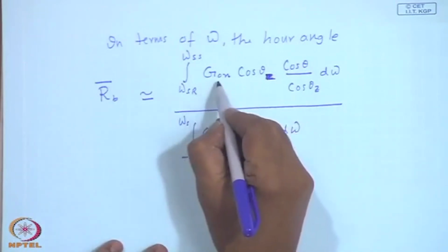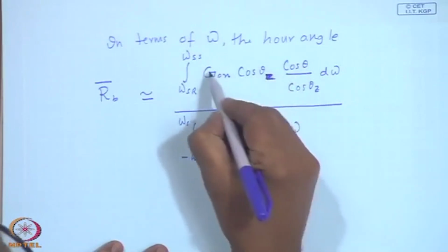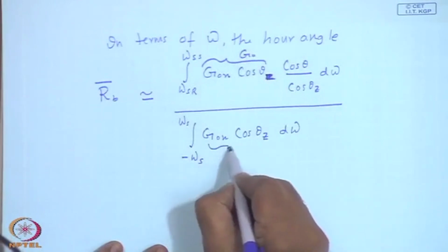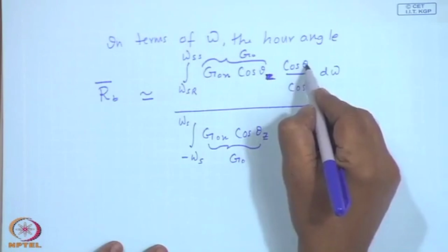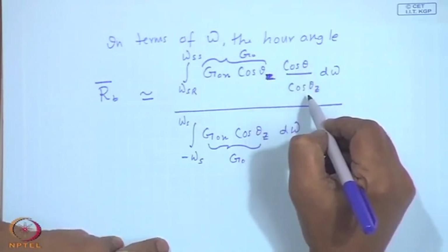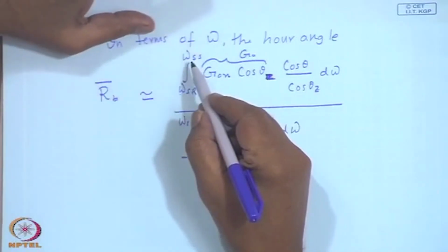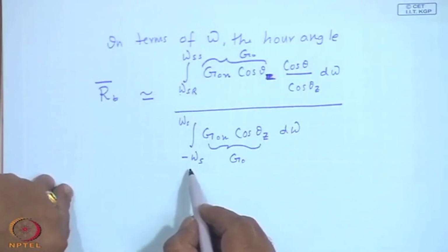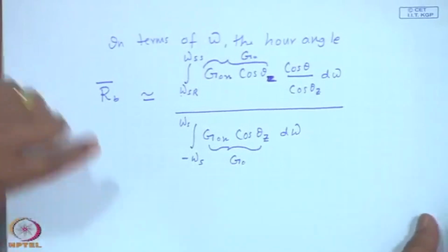So, this is the normal radiation multiplied by cos theta z, which is nothing but G0, the same G0 over here, and my RB is categorically cos theta upon cos theta z. I am now distinguishing that the tilted surface may not see the radiation all the time as the physical sun sees, the horizontal surface or above the horizon. Okay. So, let me rewrite it.